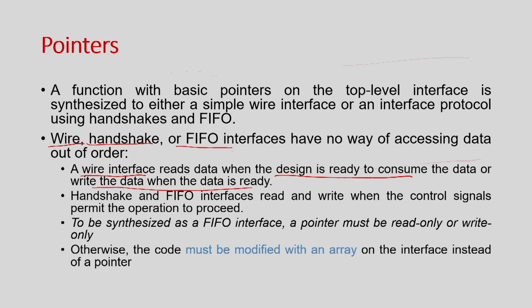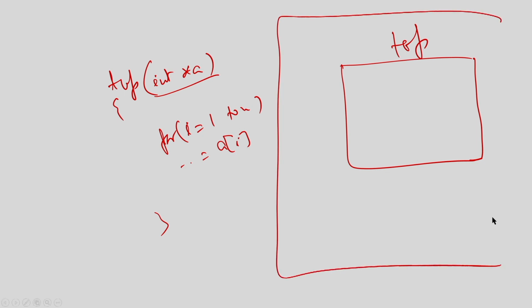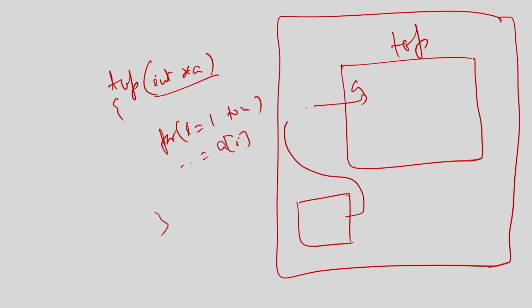So, you have to understand that whenever you have written a function, it will be implemented in your top, and it will be integrated with many other modules in a bigger system, right. So, suppose this is taking A from this function. This may not produce A in every cycle, right. There may be some latency, so say latency is 4.